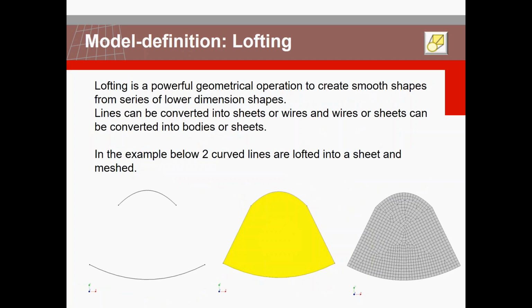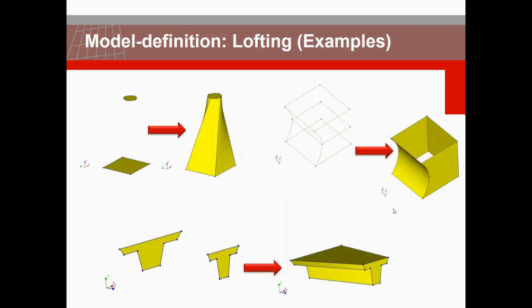With respect to model modifications, we incorporated and added the lofting feature. This lofting feature covers different settings, but long story short, it helps you upgrade your lower-stream, or say basic, geometries to upper-stream geometries. Here you can see I have two curves, and based on the loft, I can generate a surface in between, and proceed with the rest of the meshing and analysis in the model.